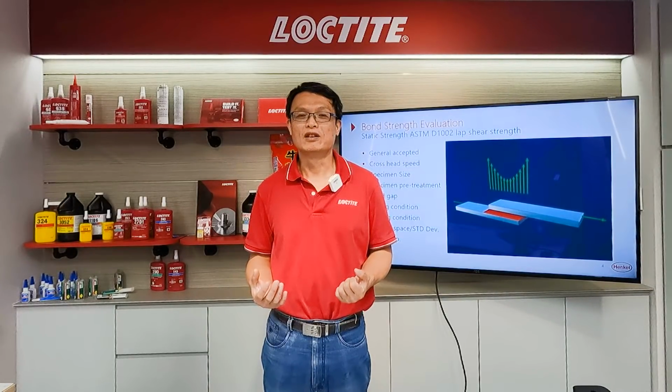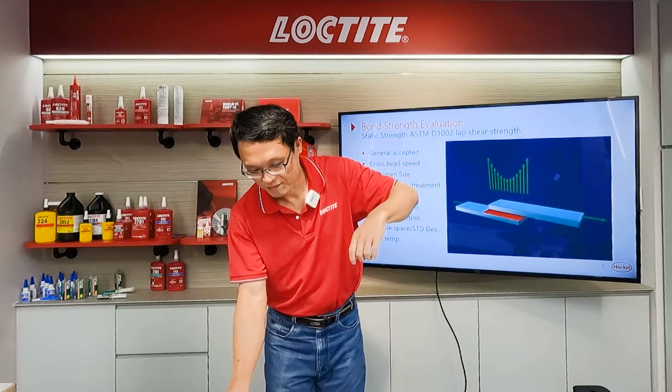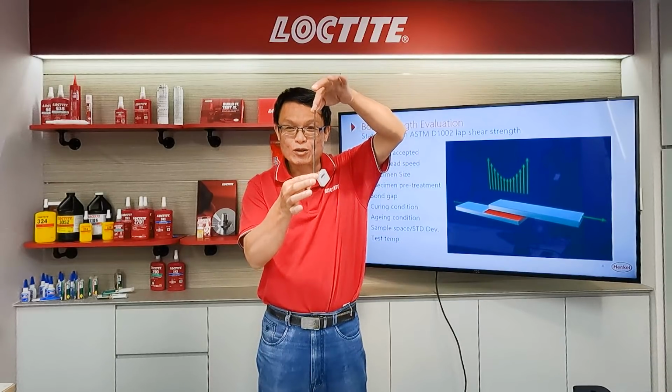What comes out is that we understand this is a static strength, because in the universal tensile tester, the crosshead will pull off the specimen slowly. So the data you can collect is a static strength. It is not a dynamic strength or vibration or impact.